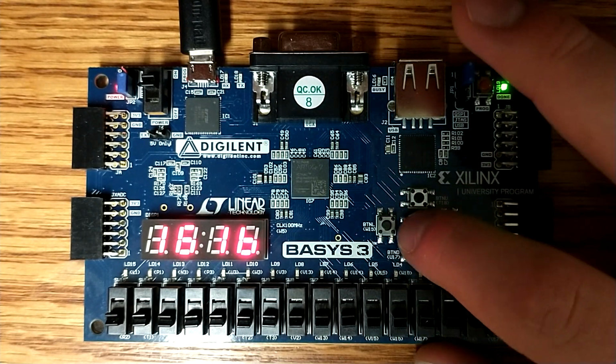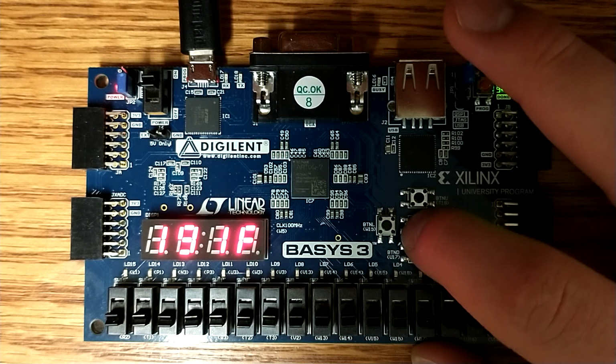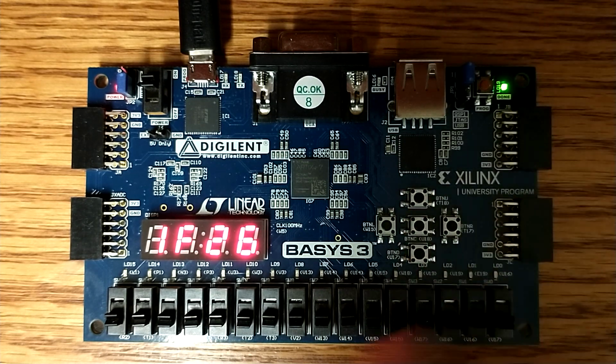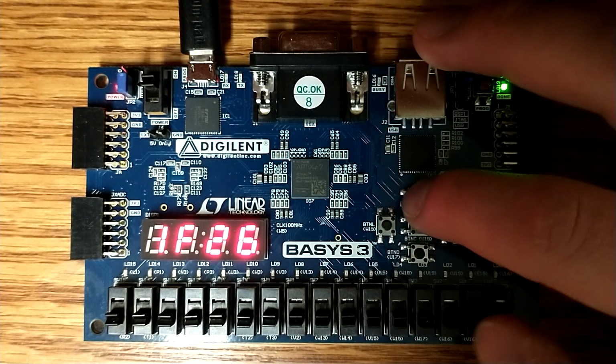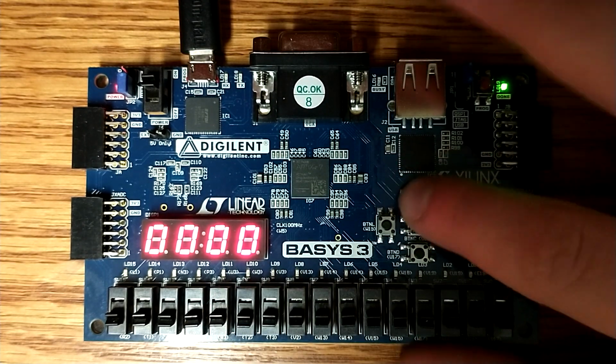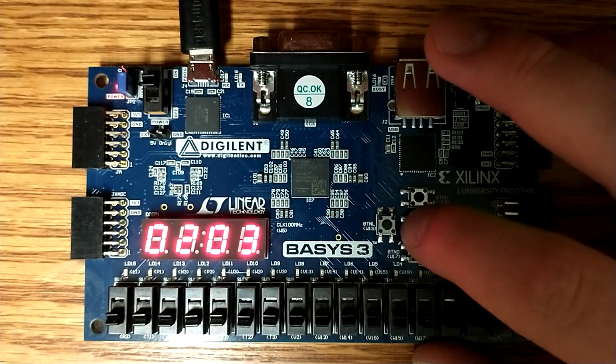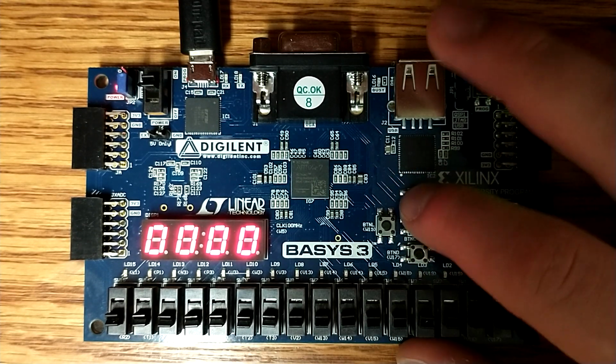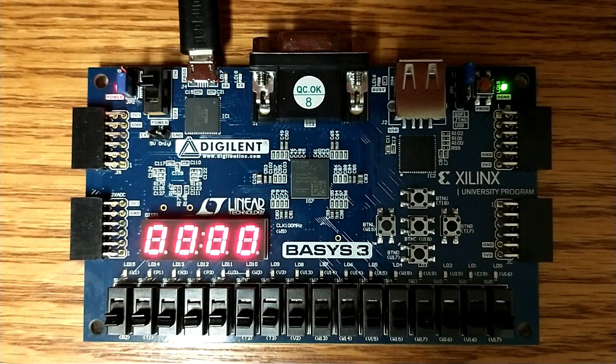We can count up a little bit more, see that it is properly registering those debounces and the bounced values on these 2 digits over here. And then we also have the up button right here, which will reset everything to 0, and it will keep counting as we keep pressing. And that should do it for Lab 8.